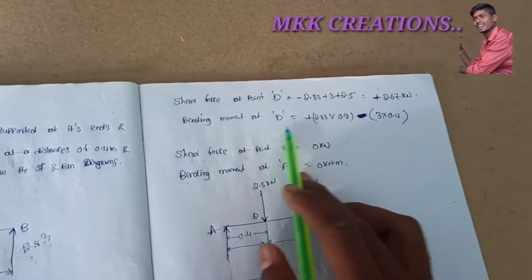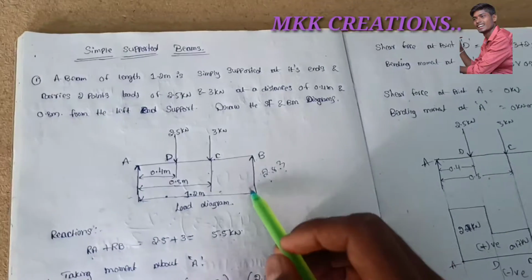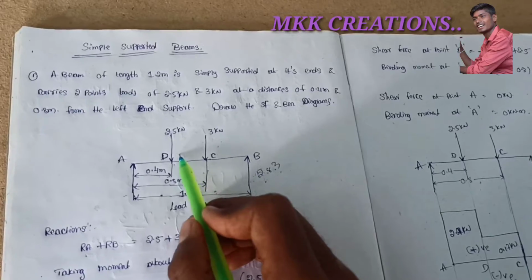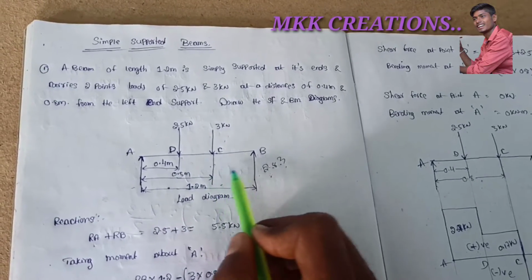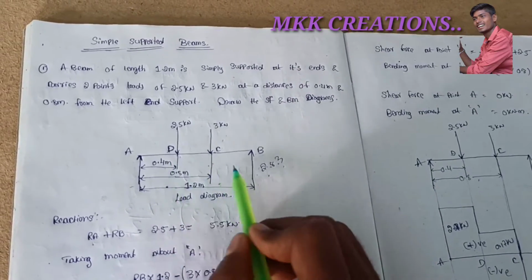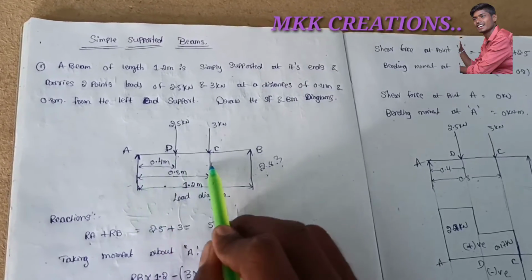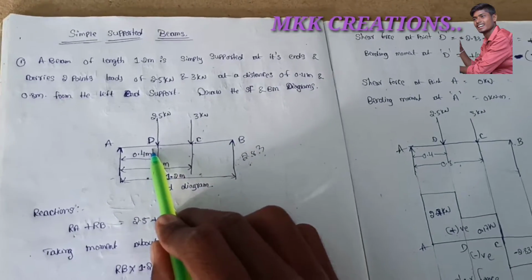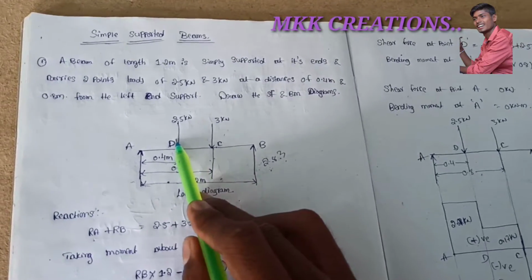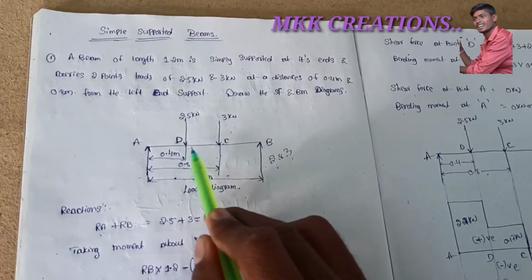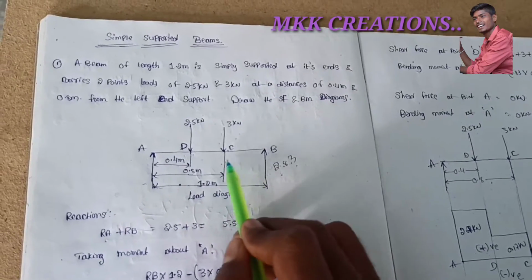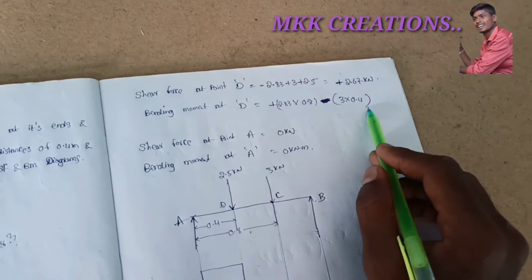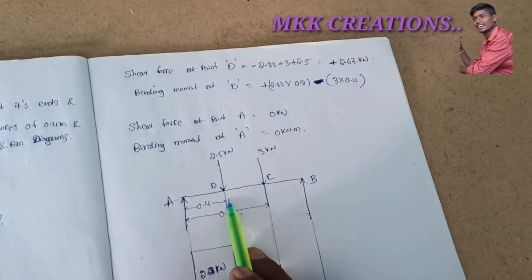Next, likewise, bending moment. So plus 2.83, towards the portion D now, into the distance for D. From B to D is 0.8 only. From A to C is 0.8, from B to D is 0.8. So 2.83 into 0.8 minus 3 into 0.4. This value is 0.4, for this value also 0.4, 0.4 plus 0.4 is 0.8. See here, at portion D, for the portion BD.